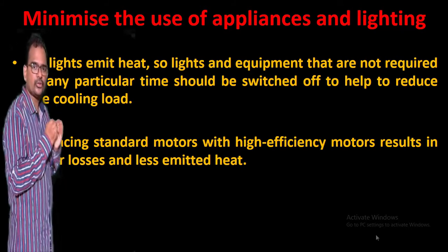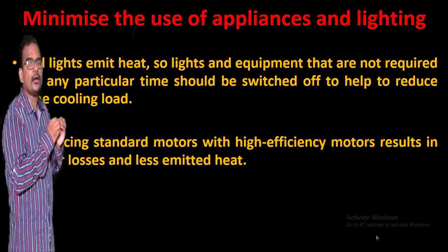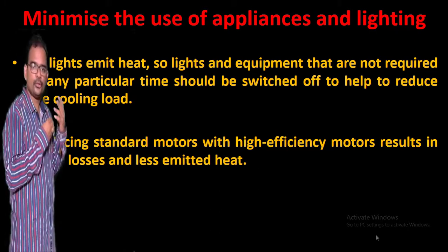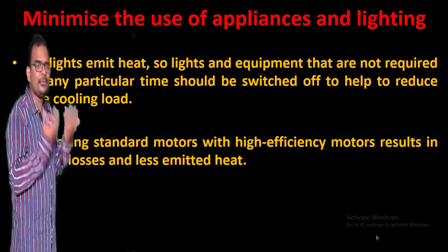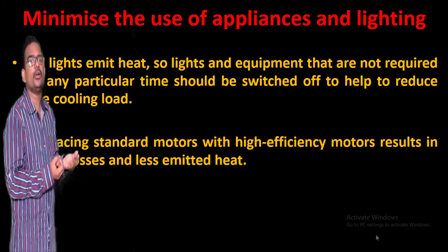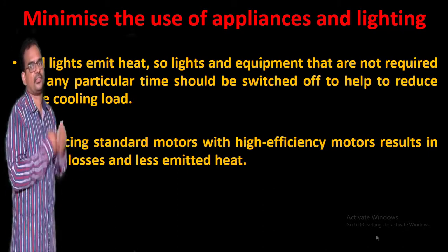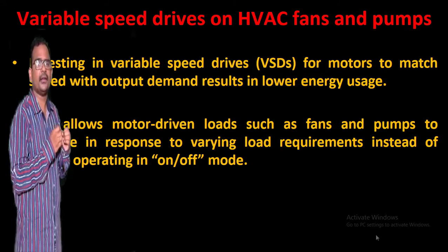Replacing the standard motors with high energy efficient motors also will result in lower losses. As we already know, high energy efficient motors will have low losses and thereby less heat will be emitted from them because of their low losses, and this will reduce the cooling load in the space to be cooled. The use of variable speed drives on HVAC fans and pumps.